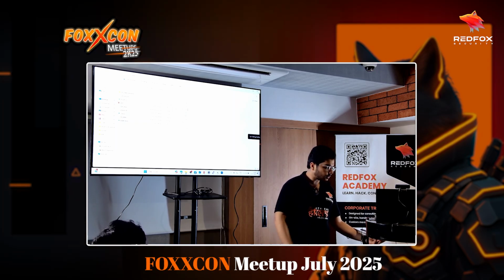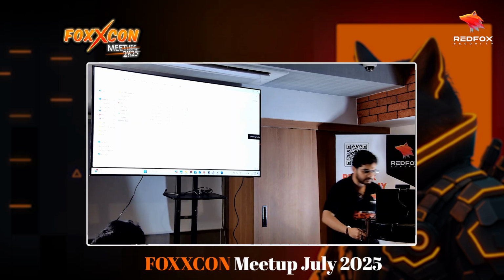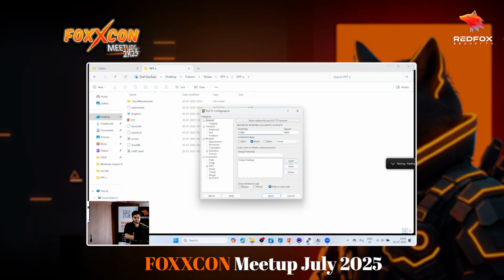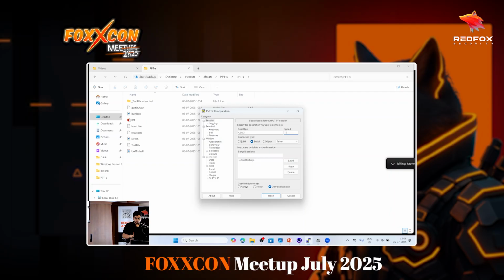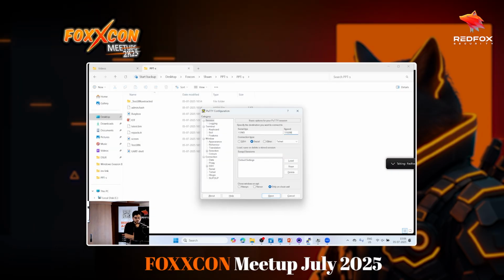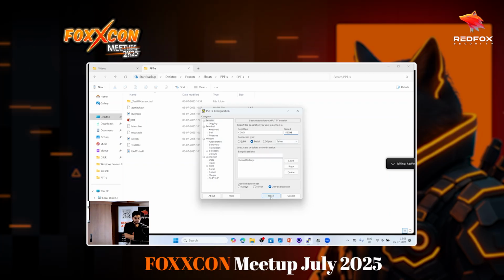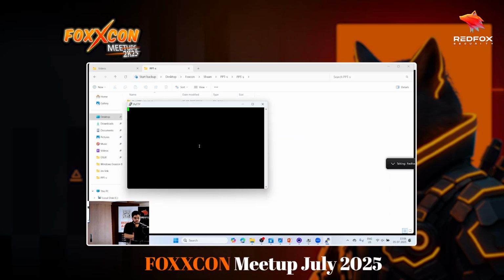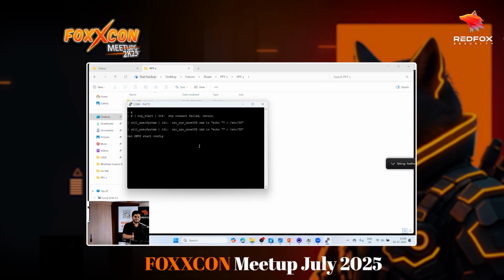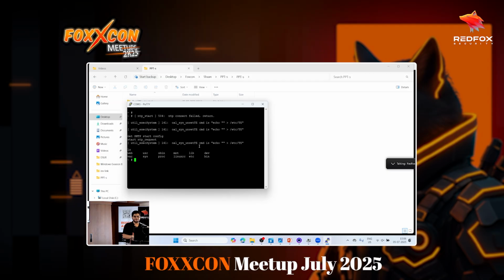Okay, so here we'll be choosing which speed we are talking about right now. In this case, we are looking at 115200. And we just do connect. It opens up a shell. Now guess what happens if I press enter? I get a shell, and if I just press ls here, it will list out the system.